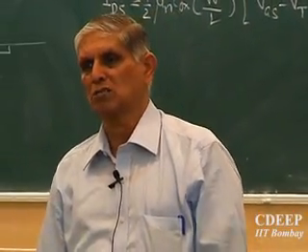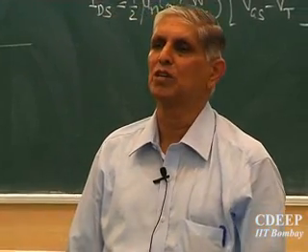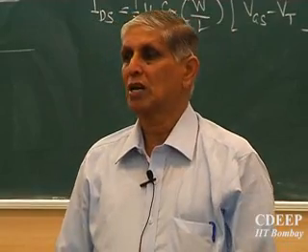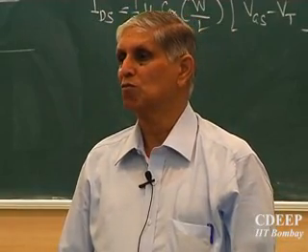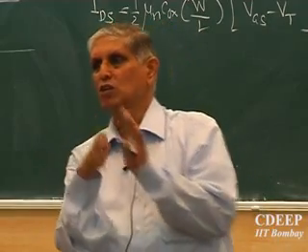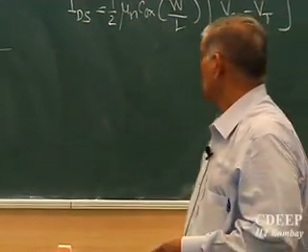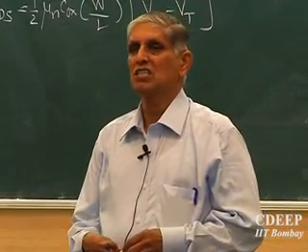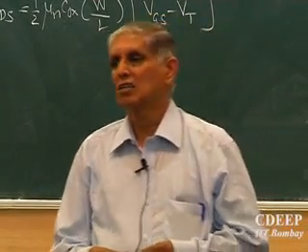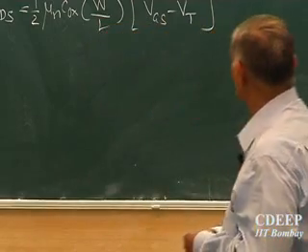Typically the input signals may vary from a few millivolts to tens or 20 millivolts, whereas DC values may range from 1.2 volt to 5 volts. So these are called small signal because the DC value is at least orders higher than that of the AC signal.